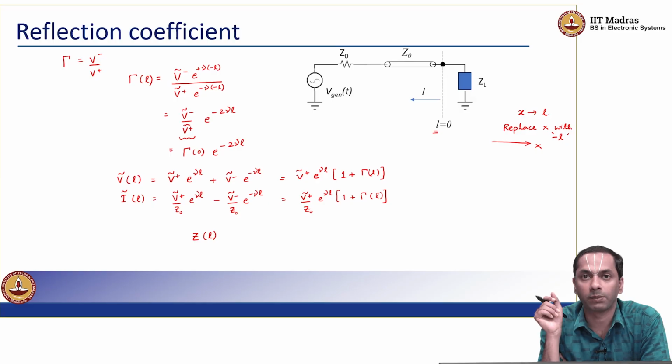And the mathematics is telling us that because of these wave-like behaviors for voltages and currents, and that these forward and backward propagating voltages constructively and destructively interfere with each other, we notice that the ratio of this voltage to current along the transmission line is now a function of where you are asking me to do this voltage to current ratio, right?